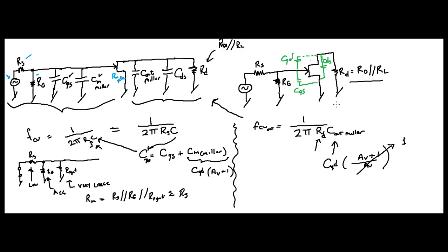Now remember how to calculate your capacitances. This is the difference, right? There are several differences. They're similar to bipolar junction transistors, but not exactly alike. Just remember those earlier equations. You can calculate them from parameters known as CRSS, CISS, and COSS. COSS is not always specified, and you need that to calculate CDS. That's why you either have to assume a value or neglect it if it's not specified.